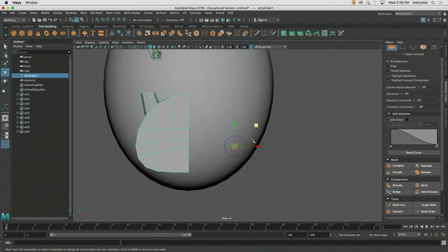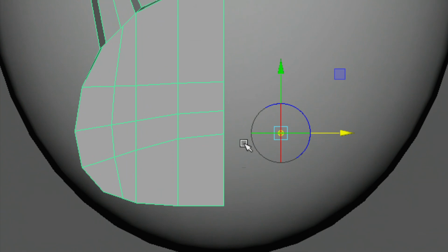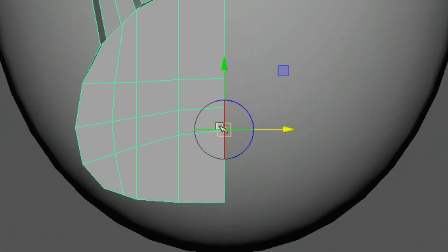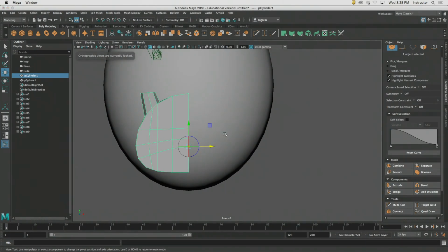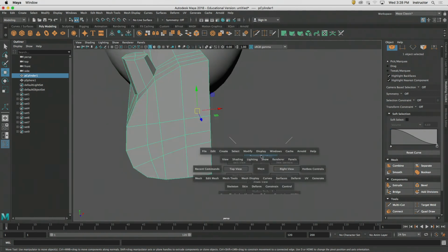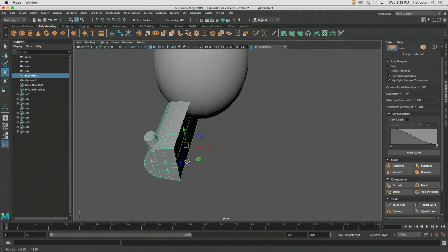Okay, here we are from the front. Now, I don't want to just hang out in here and move this where we want it to go. I want to do some vertex snapping. I want to snap the pivot point to an existing vert on the model itself. And to do that, hit the V key. V is in vertices, or Victor. Okay, and now it's going to snap to verts. Boom. And I have great confidence that my center point for my object is at the center of an existing piece of geometry. Okay, let's turn off the edit mode. Yep, I'm pretty happy about that.